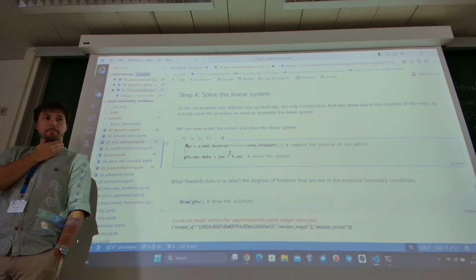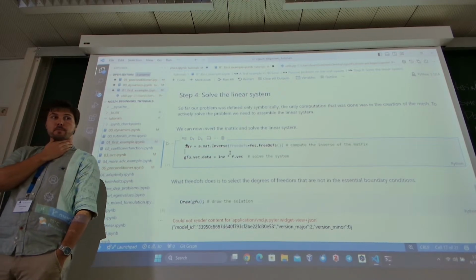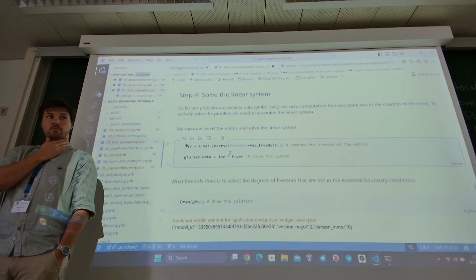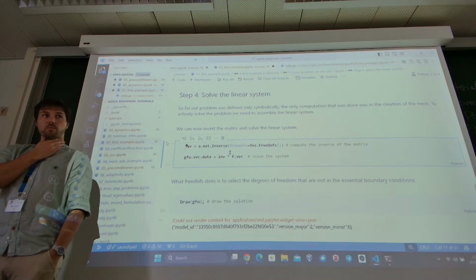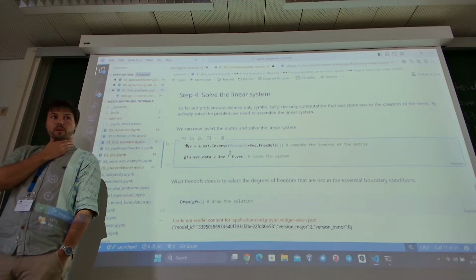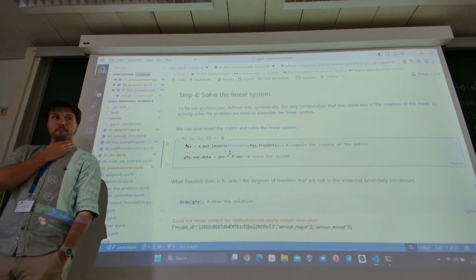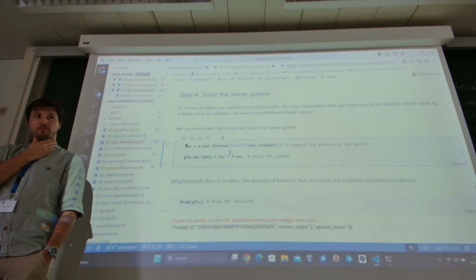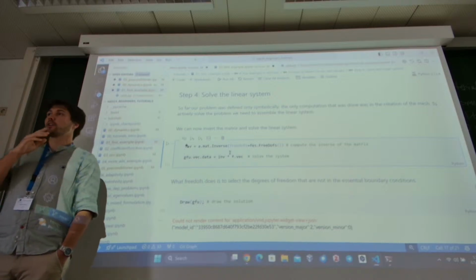It depends on what kind of direct solver you're using. So Umfpack, Pardiso and Sparsecholesky behave differently. Some complain that the matrix is singular, some survive. So you should know that you have a singular matrix, and you should not do it.